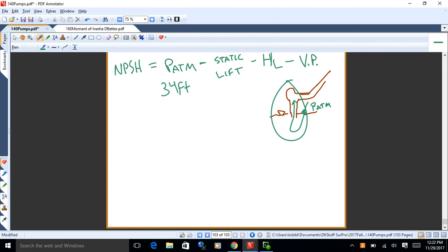Okay, different pump heads. Let's see, there's static and dynamic. Static is when you just lift water, you're just looking at the elevation you're lifting water to. And then dynamic is when you're actually pumping the water and you get head loss. Okay, horsepower, you got water horsepower, then you use efficiency to find brake horsepower and motor horsepower. And then electric power costs.